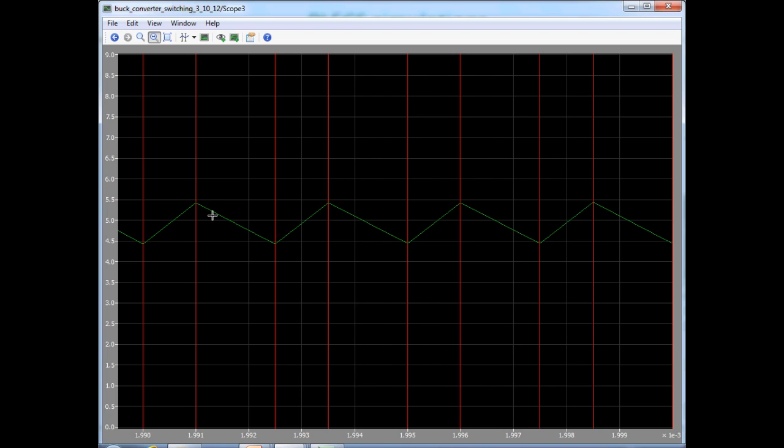And also notice that our worst case for inductor was the minimum duty ratio, or the maximum input voltage, which is exactly what we are doing the simulation for right now. So this does correspond to the worst case, and our worst case value of peak-to-peak inductor current ripple is exactly what we designed for, of 1 ampere. Okay.